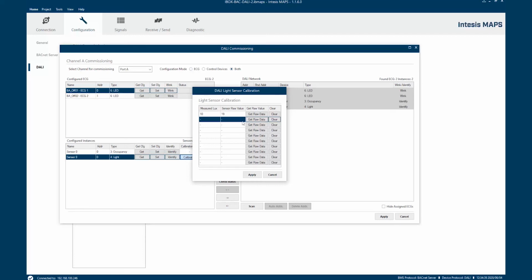So now, for example, I'm going to do another measurement, which is I'm going to cover my sensor, and now, as you can see, I have less light. It's measuring there, but the right measurement should be 0. I'm going to set it there. And now, for example, I have a flashlight here. I'm going to point the sensor with my flashlight. We see that we have a lot of light over there. So I'm just going to say that this one is 100.